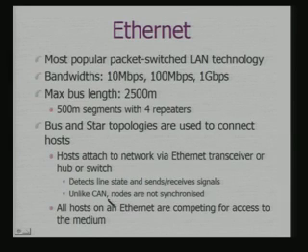But what is fundamentally different from CAN is that nodes are not synchronized with respect to a universal clock. If you remember, in CAN, all the nodes which intend to transmit a frame will start transmission at the same time.